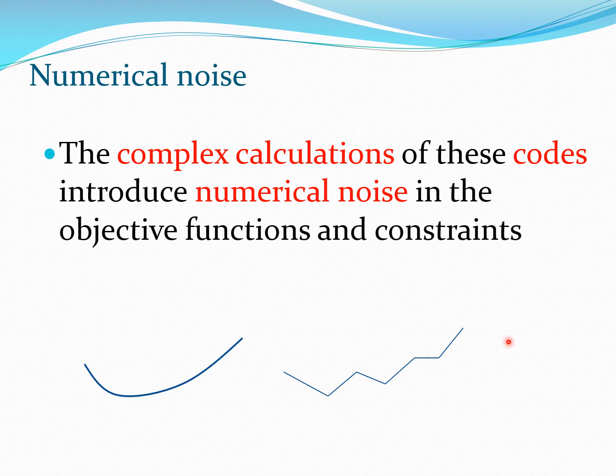and the smoothing could be done using a response surface. So this is one more advantage of a response surface. And we have done problems where we have used rough convergence criteria. That is, instead of converging your code to say 10 to the power minus 10, you could converge it to 10 to the power minus 2. And that would save a huge amount of computer time in many numerical simulations.